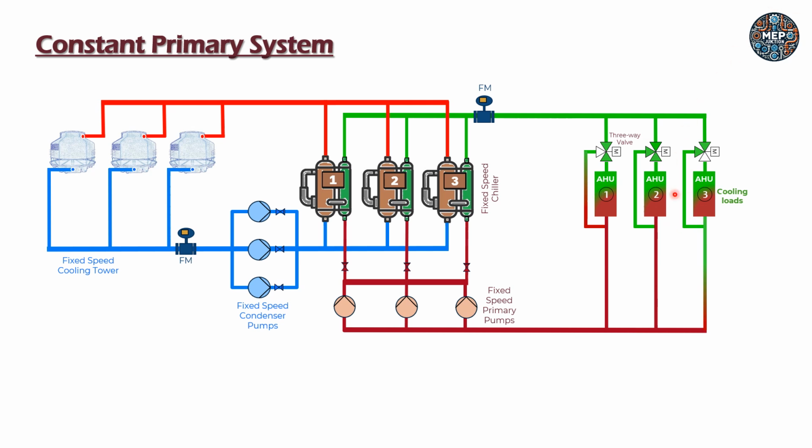The air handling units are used to control and maintain the indoor air temperature, humidity, quality, and comfort. Here we will understand how chilled water is circulated through this AHU, and warm air entering the AHU passes over the coils to transfer the heat to the cold chilled water to have the cooling in the air, right?